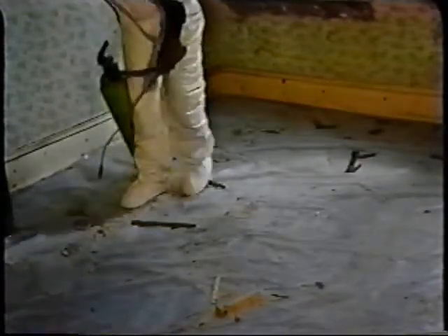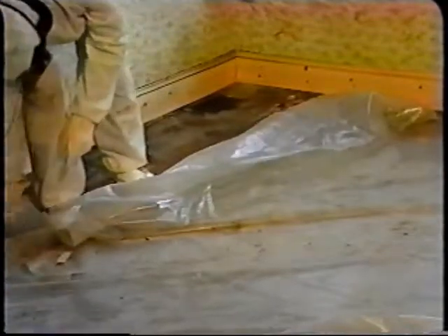A final cleaning should be conducted after all abatement and interim control activities. Final cleaning begins with the removal of all plastic sheeting from the work area. Lightly wet the entire surface of the plastic with a water spray to minimize dust. Then carefully unseal and fold the edges to the middle to trap dust or dirt. After the plastic has been folded to a manageable size, insert it into a plastic bag and seal it for removal to an appropriate landfill.